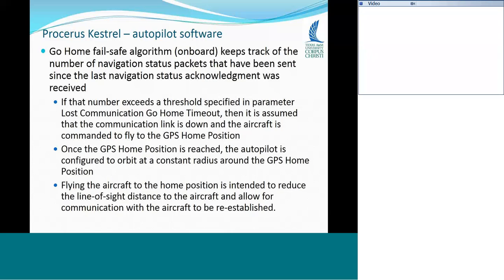And it's the same kind of thing. There's an acknowledgement ratio on the ground control station also, because it's sending packets up to the airplane and then checking to see if it gets an acknowledgement. And so there's a ratio. Maybe it's getting 95% acknowledgement. It's missing a few, but yeah, that's okay. But if it drops below some value, then there's a possible issue. And if it drops below another value, then it's considered lost. And if, of course, it's not getting it at all, then that's how you know on the ground that you've lost link. So that's happening on both ends.